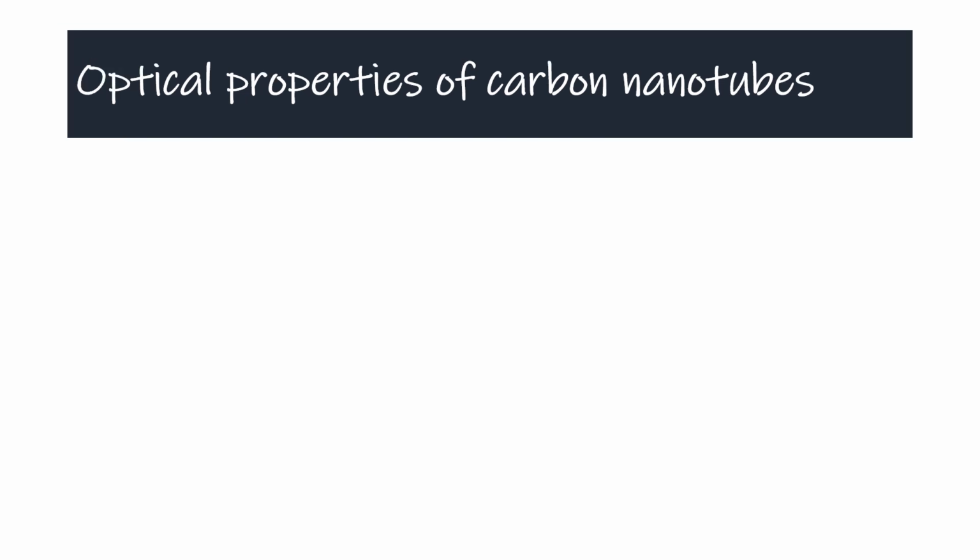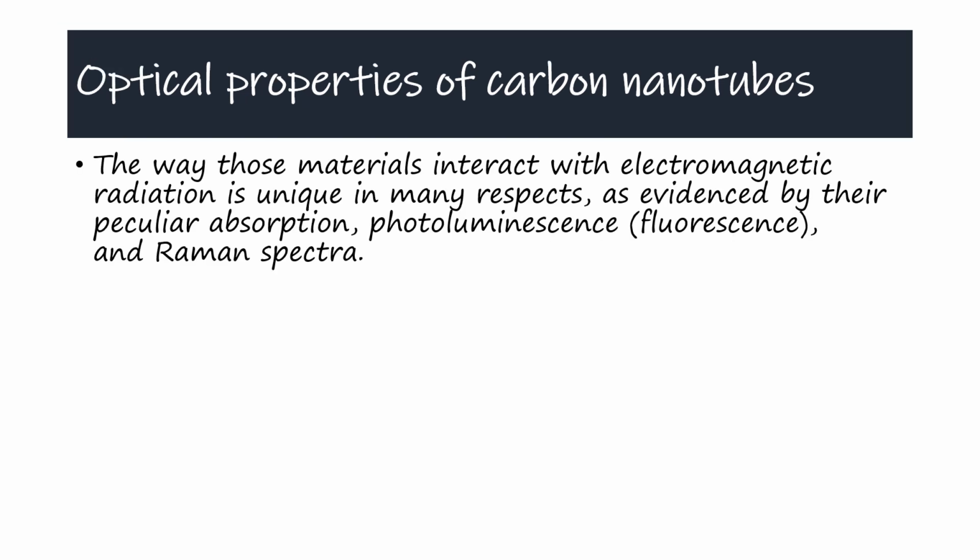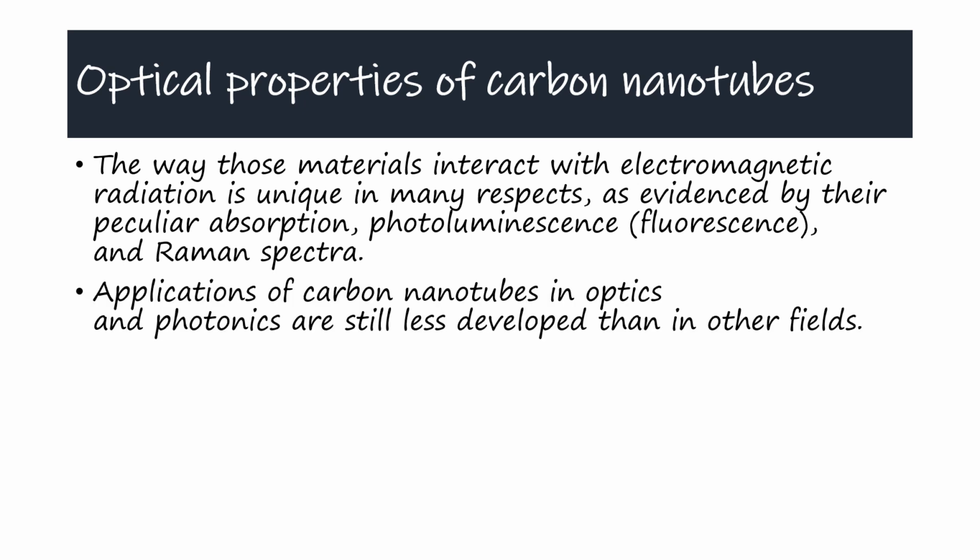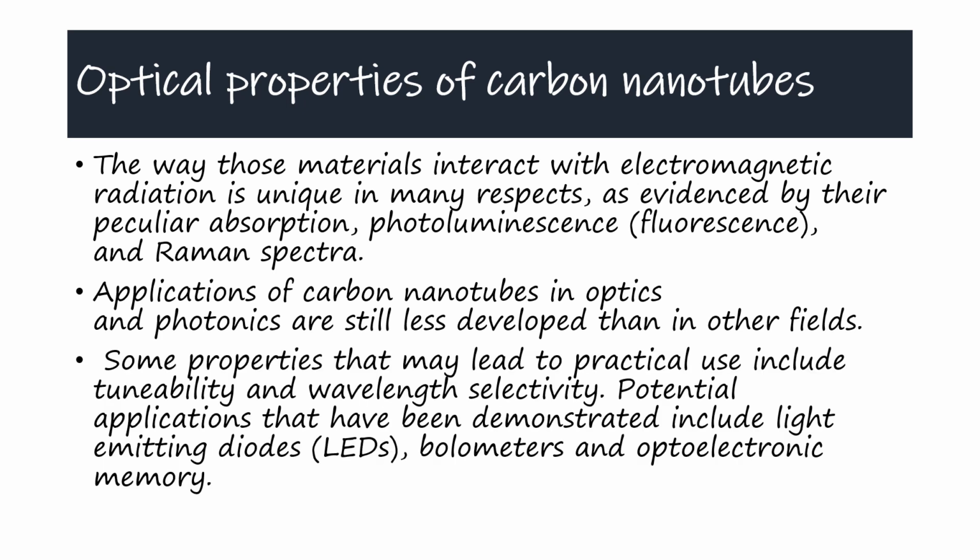Let's see the optical properties of carbon nanotubes. These materials interact with electromagnetic radiation, and show peculiar absorption, photoluminescence, and Raman spectra. Applications of carbon nanotubes in optics and photonics are less developed, and some properties may also lead to tunability and wavelength selectivity. Potential applications that have been demonstrated include LEDs, bolometer, and optoelectronic memory.